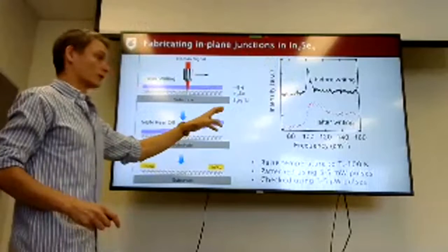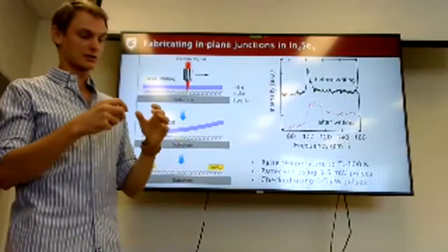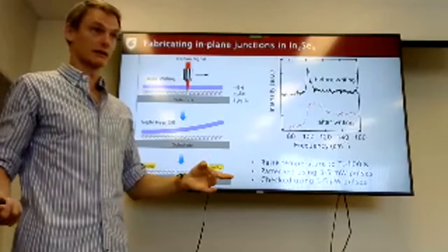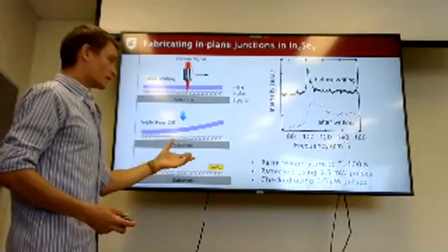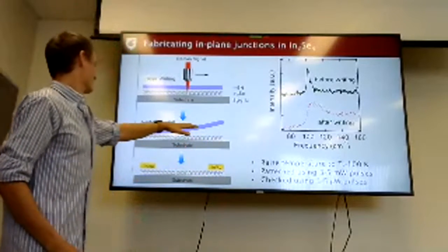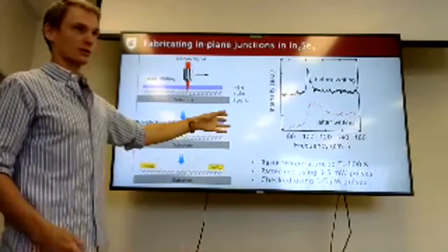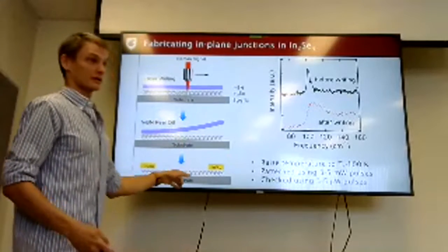And we had a lot of question of whether it would be stable at room temperature, right? Because now you have lattice mismatch. You have a beta phase buried inside of an alpha phase, and when you bring it back down to room temperature, it might not be stable, right? It was, which is great. So then we could peel off the hBN, we place gold electrodes or indium gold electrodes so that the work functions work out. And now we have a device.